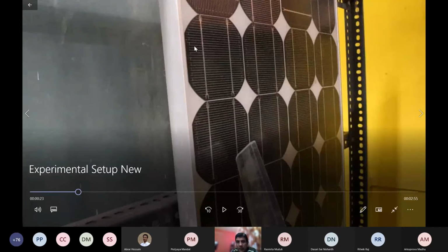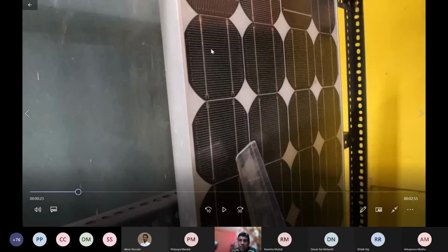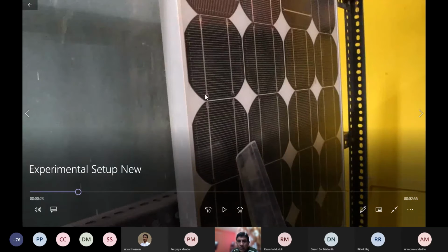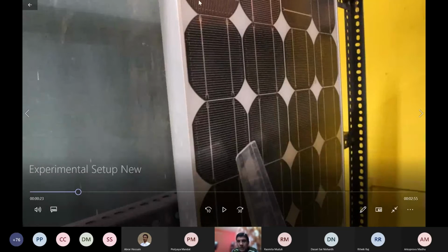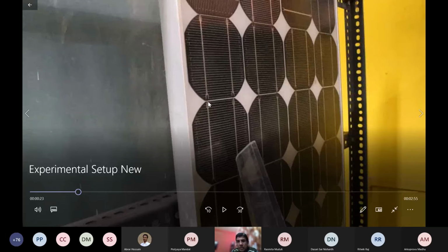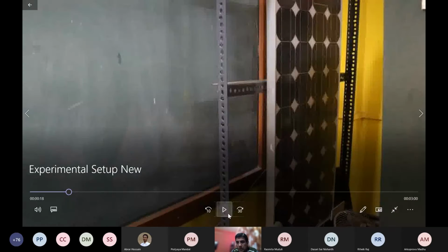These are actually metal masking. It is only to capture the electrons which are liberated after the photon falls on it. Then there is a perpendicular thick line which will further collect from those horizontal lines, and these are further connecting one cell to the other cell in series. So the whole lot is coming in this way.